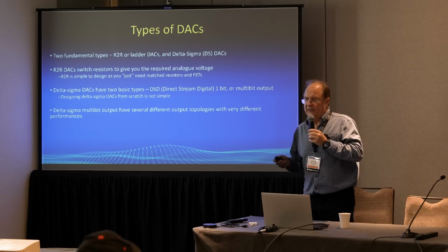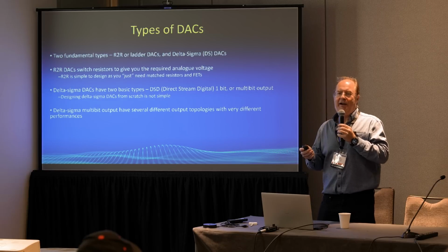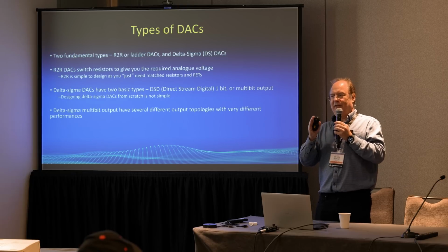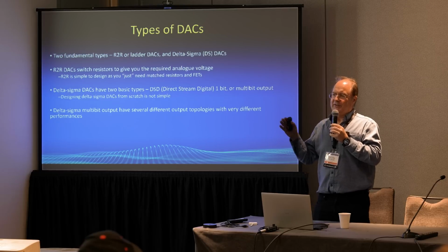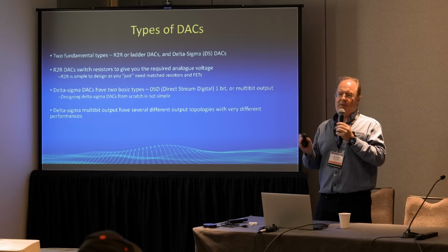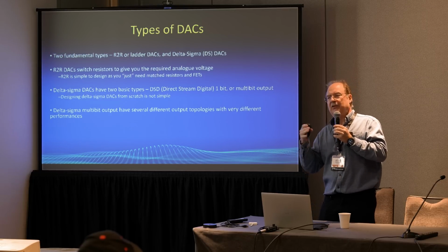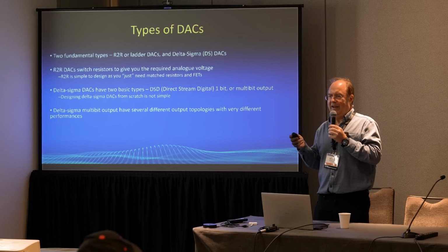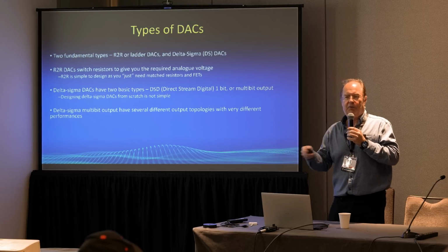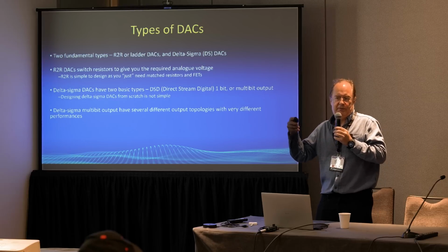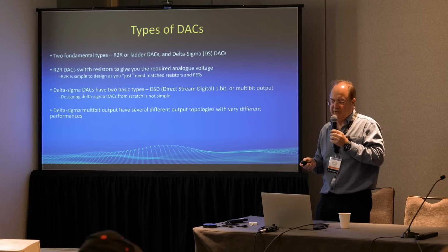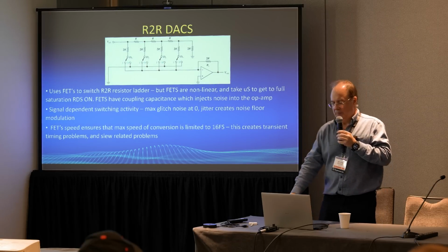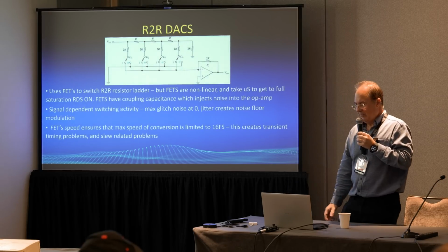Now, delta sigma DACs have very different topologies, and to say a delta sigma DAC sounds a particular way, or that all delta sigma DACs sound the same, is incorrect because you've got so many different flavors of delta sigma DACs. I'm not going to be talking about every single flavor that you can get. I'm going to be talking about the broad brushstrokes of types of delta sigma DACs that you've got. So firstly, let's talk about R2R DACs.